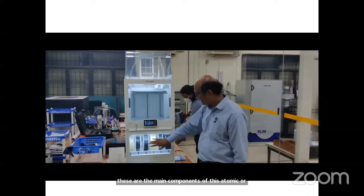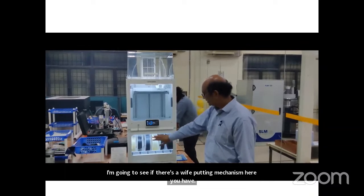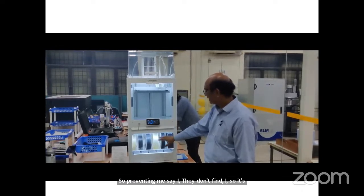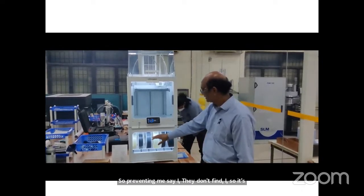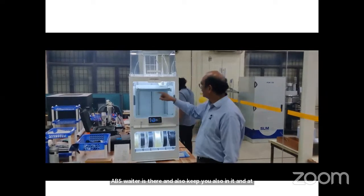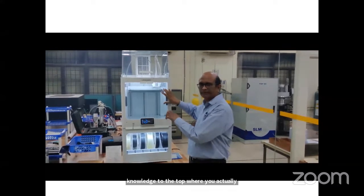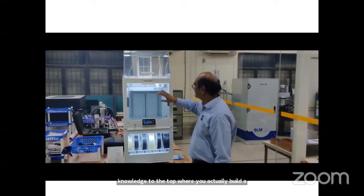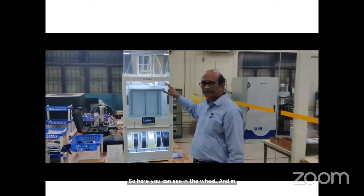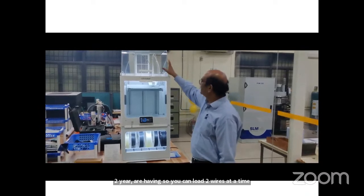Here you have the wire feeding mechanism. Presently in this S5 Pro we are loaded with around 5 types of materials: PLA, tough PLA, ABS, and also TPU. You can see that presently this wire is being drawn by the nozzle to the top, where the entire part will be built. Here you can see the build platform, and this is the dual extrusion nozzle. You can load 2 wires at a time, 1 wire for the supporting material, 1 wire for printing the part. And this is the air manager chamber here.